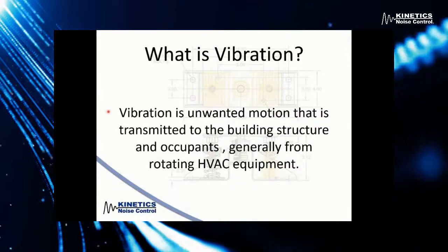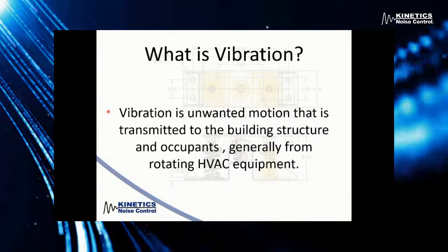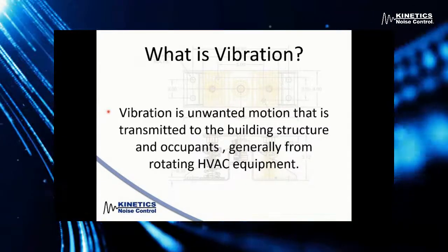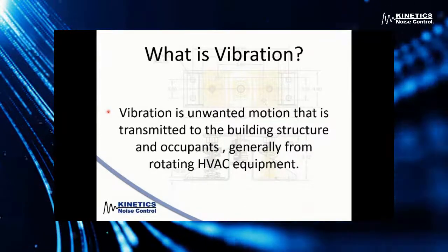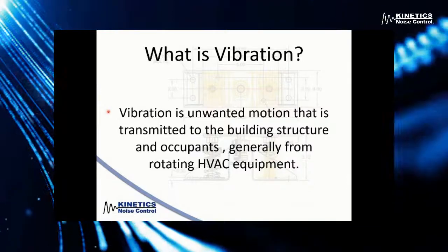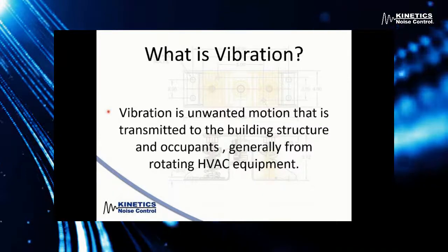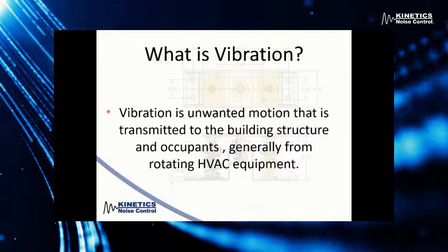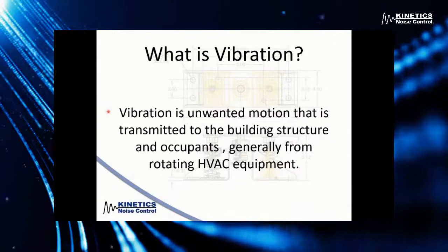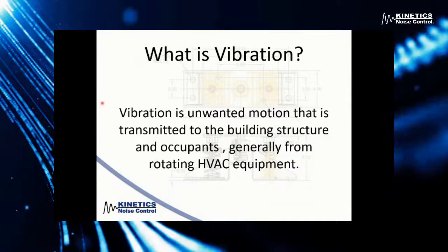And the main overlooked part of vibration isolation isn't just the noise it makes. It's the fact that modern commercial buildings are made up of structural steel columns, and that vibration can get into the steel structure of the building and cause a tuning fork effect. You can actually see degradation and damage to the building structure over time when this vibration gets down into the building.